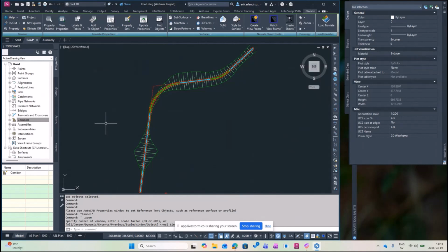We actually got one question about the update, but you answered it so beautifully in the end. So about updating from the corridor. I can add that as Eric showed now, we have update with when you do slope patterns from a corridor, they need to update. If you do slope patterns for other feature lines, which works the same functionality, in that case, you can actually have the slope patterns be dynamic. But for corridors, you need to run an update for them. So that was the only thing that I wanted to add.